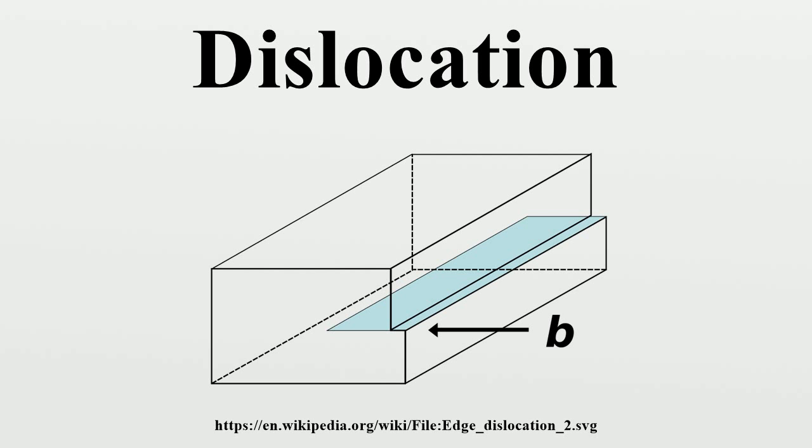There is an alternative mechanism of dislocation motion, fundamentally different from slip, that allows an edge dislocation to move out of its slip plane, known as dislocation climb. Dislocation climb allows an edge dislocation to move perpendicular to its slip plane. The driving force for dislocation climb is the movement of vacancies through a crystal lattice.